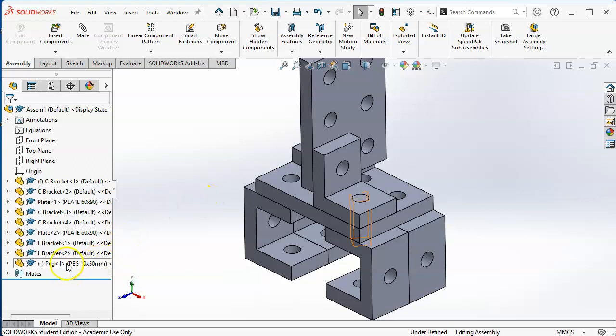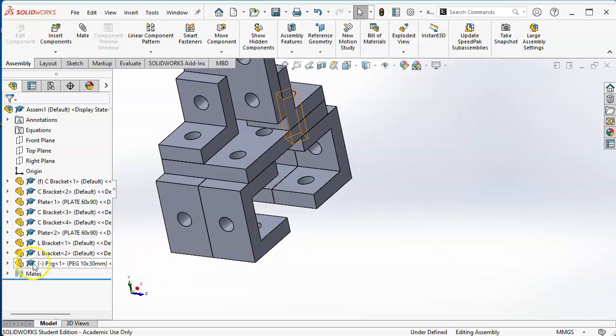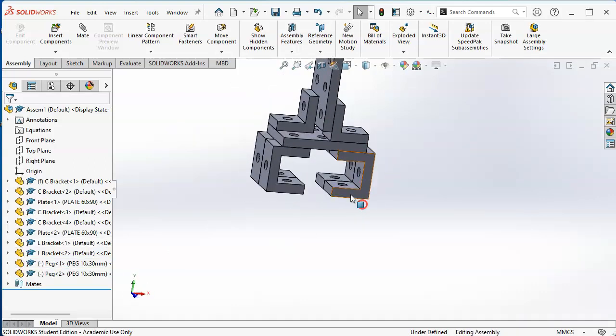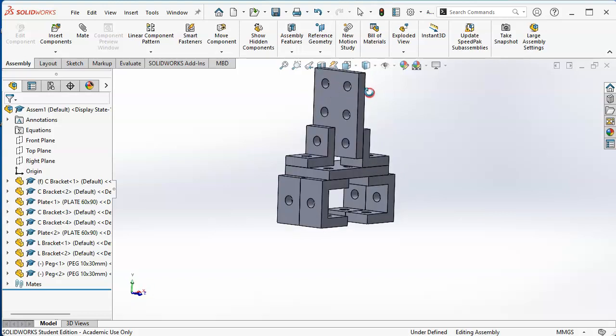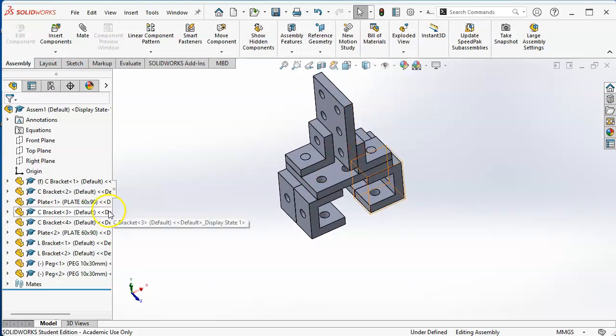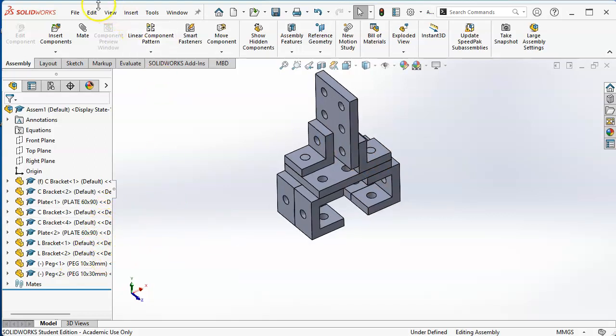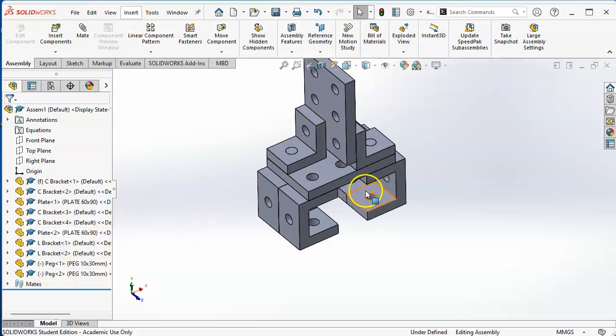So let's go ahead and we'll bring in the next 10 by 30. All right, and then this becomes the contortionist act, where I have to thumb on the control button, left mouse holding down, index finger tabs, let go, and let go, or some order like that. So, all right, we have the 10 by 30. I could go back to the insert components. Notice too that I did not get the concentrics on that one. So let's go ahead and go this way.